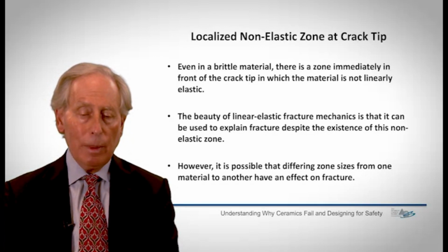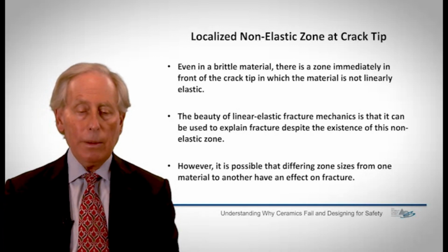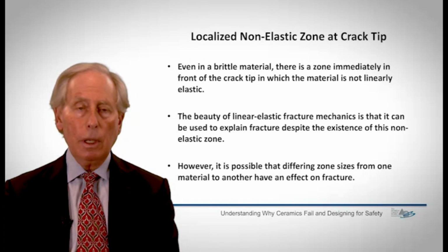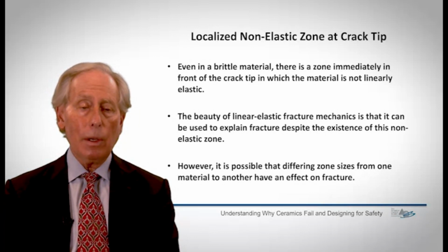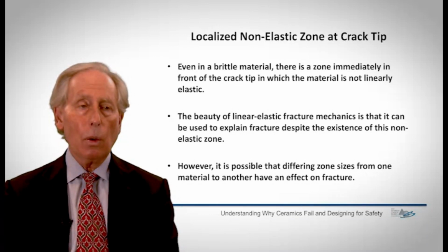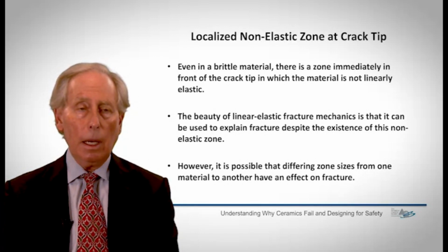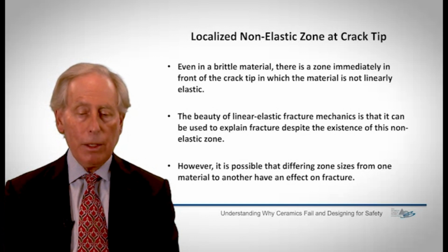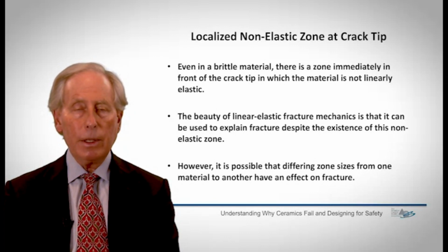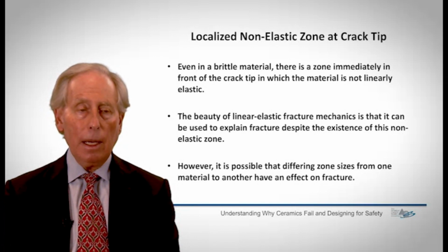However, the beauty of fracture mechanics is that it can be used to explain fracture despite the existence of this non-elastic zone, and the people working in fracture of metals do this to a great extent. We don't worry about it so much in ceramic materials because the size of the zone is so small that we pretty much ignore the fact that it exists. However, it is possible, and this is something that's really unknown, that differing zone sizes from one ceramic material to another can have an effect on fracture. But we're really not sure at this point. A lot more research is going to be needed to understand what the effect of that differing zone size might be. But just to recognize that no material is linear elastic up to the point of the crack tip itself.